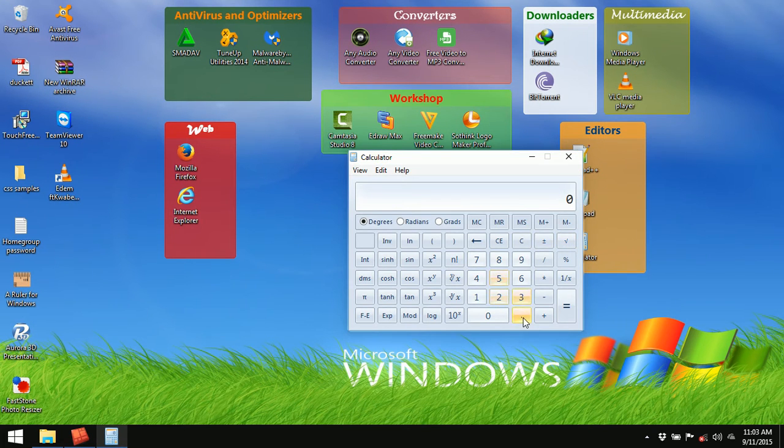75% of 1.5, which is 0.75 multiplied by 1.5, is equal to 1.125, meaning that 1.125 meters out of the 1.5 meter interval is what will be used in the calculation of the digitized segment grade. 1.5 minus 1.125 is equal to 0.375.